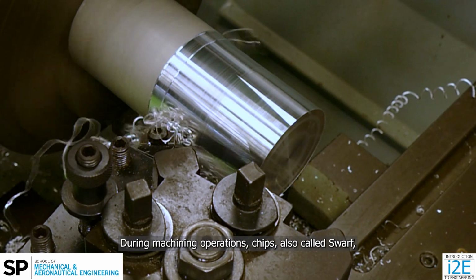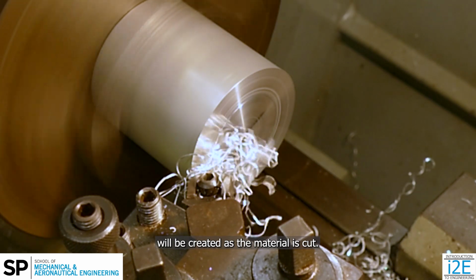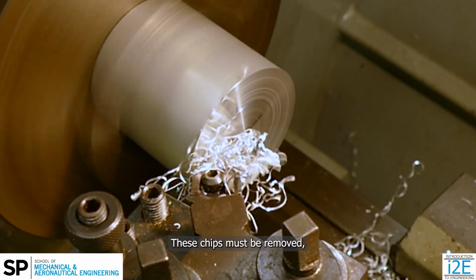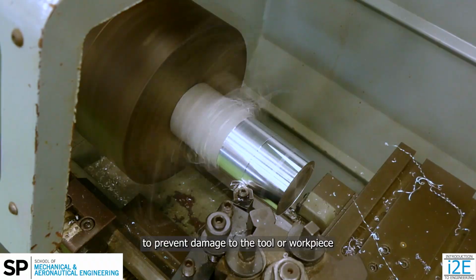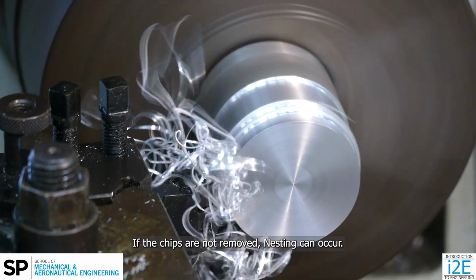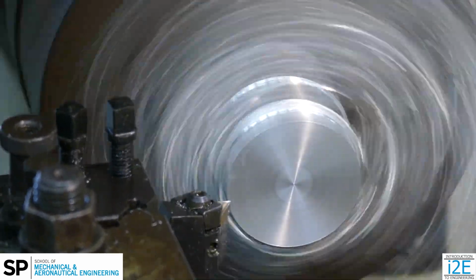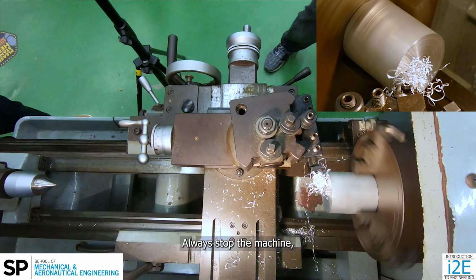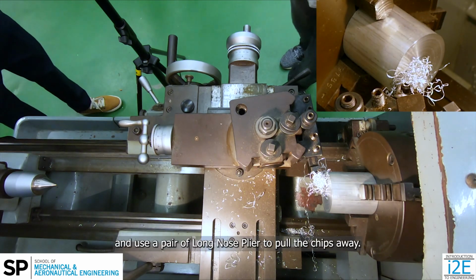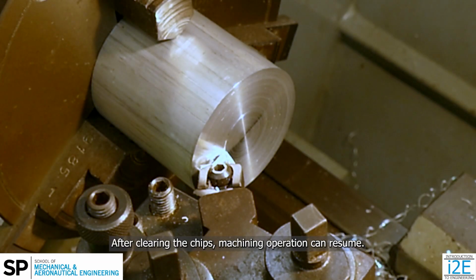During machining operations, chips, also called swarf, will be created as the material is cut. These chips must be removed to prevent damage to the tool or workpiece and to maintain operator safety. If the chips are not removed, nesting can occur. Always stop the machine and use a pair of long nose pliers to pull the chips away. After clearing the chips, machining operations can resume.